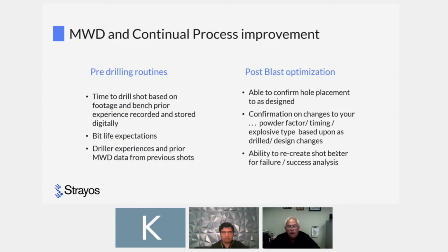Continual improvement process. This is really important. Time to drill the shot is based upon footage and bench prior experience. And now we record it and store it digitally. And it's no longer that the driller was down for a half hour. It was he's waiting for fuel is why it took me longer to drill a shot. I know why it took me longer to drill a shot. I see his actual penetration rate. Did he get stuck in the hole? What happened there?